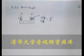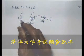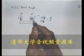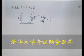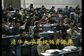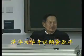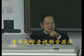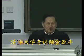But of course, if you do work on it, if you press this down by 1 inch, if this area is very large, this displacement is very small. So you gain by having a much larger force, but you have to press a large distance. If you want to do any work, you have to press a large distance and raise this side by a small distance.